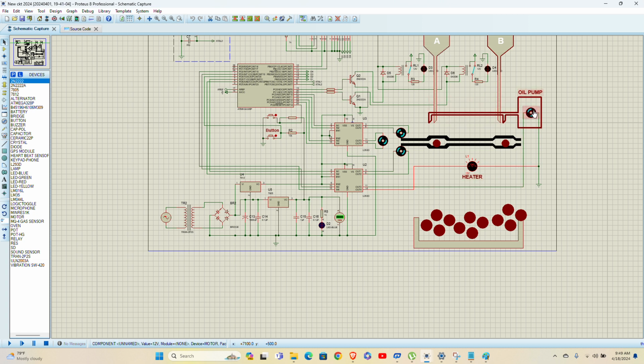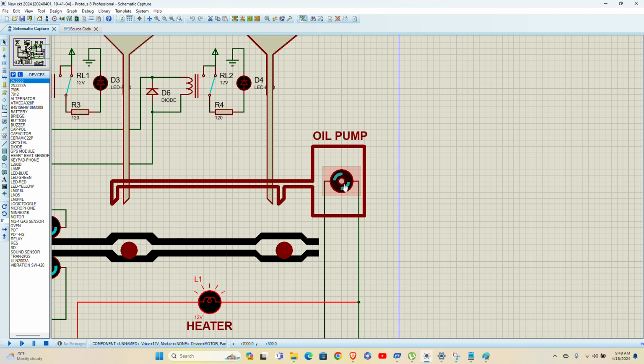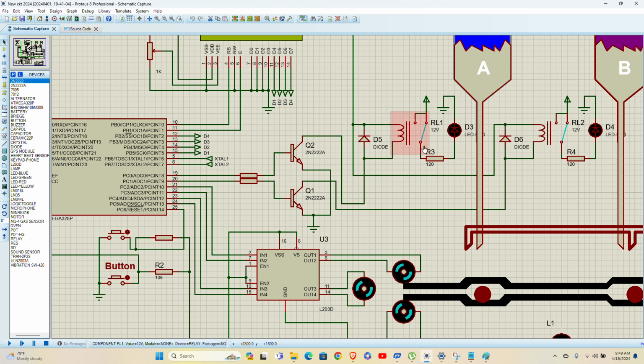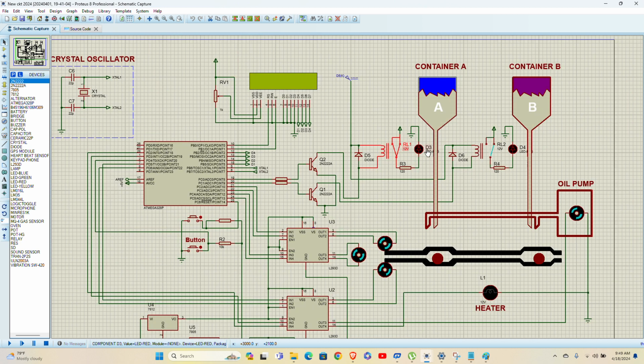So this is just the arrangement of motors and pumps. I've also used this to drive a heater, because the heater I used here is a 12V heater, and I don't know about the final implementation, since I could use more than 12. So I'll change this driver according to specific needs. The pump is the same, we use 12V, but when it comes to this little valve, we have two transistors here which drive this relay.